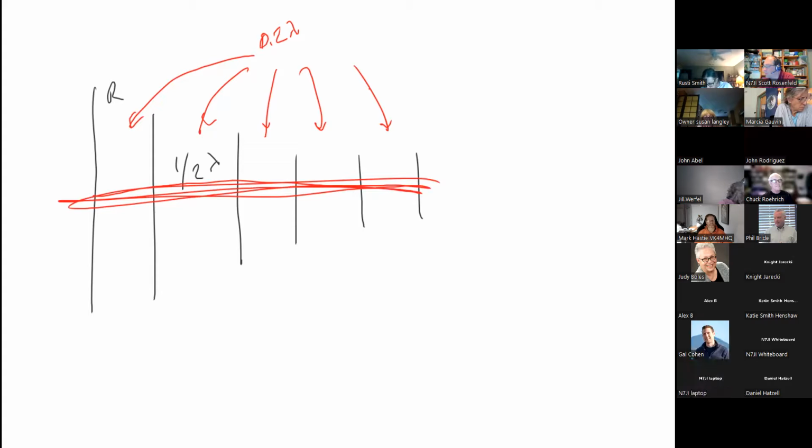The main part of the antenna is the driven element, which is half a wavelength, 35 centimeters. That's where your coax cable goes. On a 70 centimeter antenna, this is about 35 centimeters long, which is about 13 inches. And then the horizontal line will just be a conductive material connecting. No, it's non-conductive. That's usually PVC.